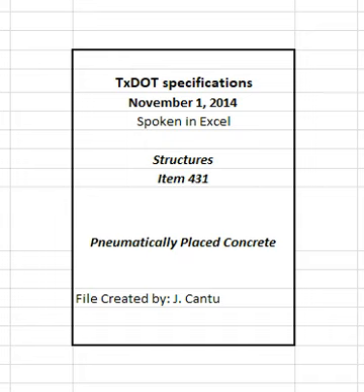3.4.1 General. Place the concrete when the ambient temperature is above 35 degrees Fahrenheit and rising and material temperature is between 50 degrees Fahrenheit and 90 degrees Fahrenheit for wet mix and below 100 degrees Fahrenheit for dry mix. Do not place concrete against a surface containing frost, ice, or standing water. Protect concrete from freezing or quick drying after placement.